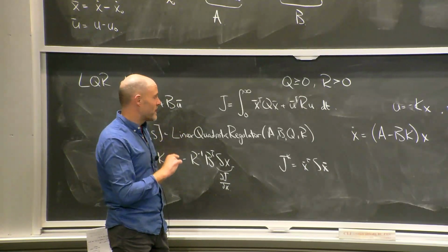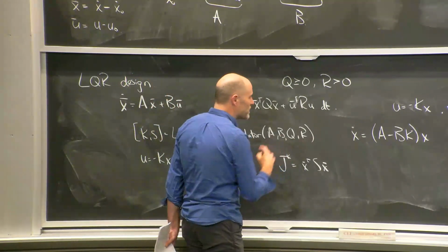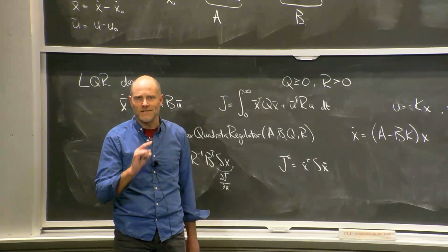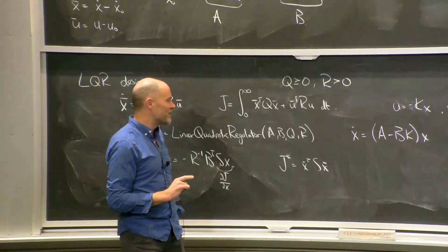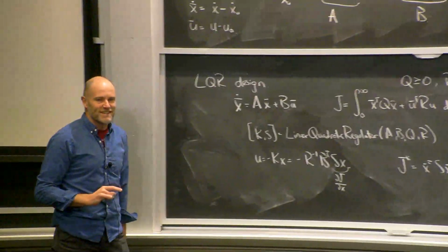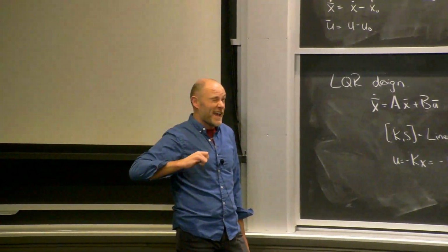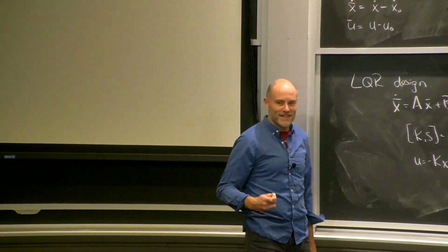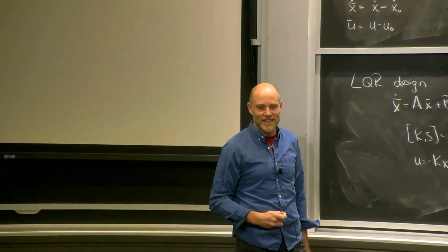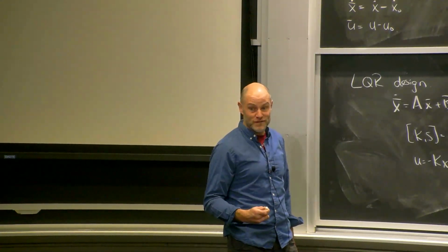If you have a discount factor, you could choose a Q and R and get a K that is not stabilizing. Just chew on that. Adding a discount factor is like being overly optimistic about your dynamics. It's like pretending your dynamics is more stable than they actually are, and you can trick yourself.